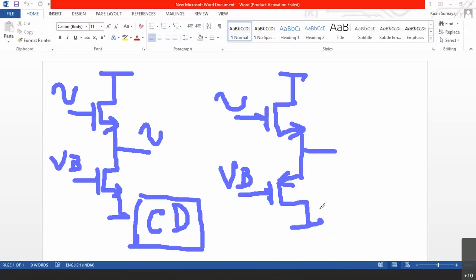But in this case, as we are using it as a resistor, we can use P MOSFET in this way also, because if you want to have a resistance, we can have it. So this is another option of having a P MOSFET as a resistor. Now my next question is, if at all we want to use PMOS only as a common drain amplifier, can we connect it? Instead of N MOSFET, let us say we want only P MOSFET.